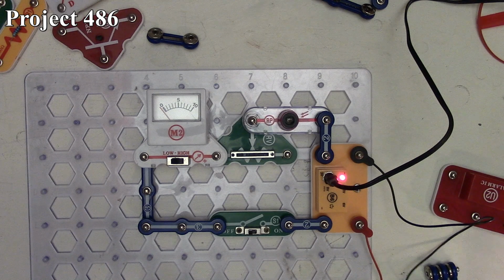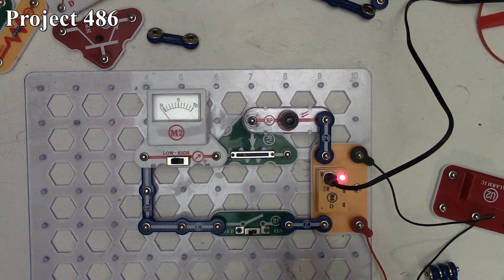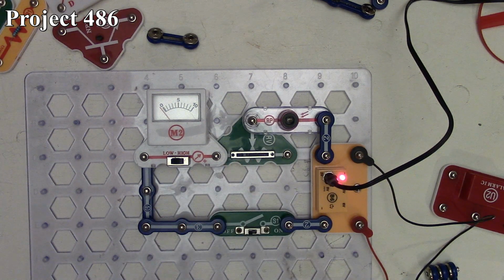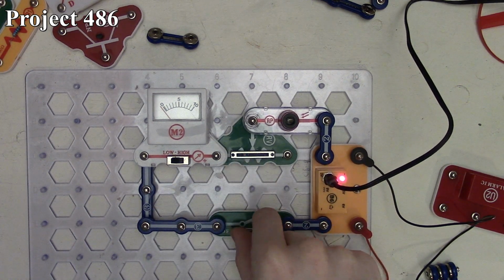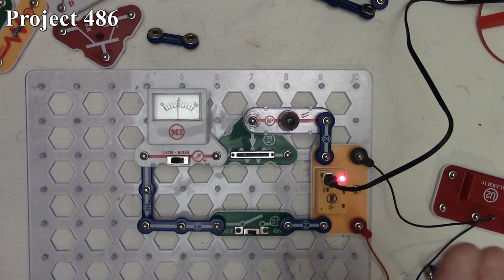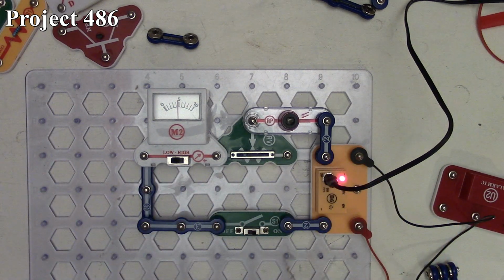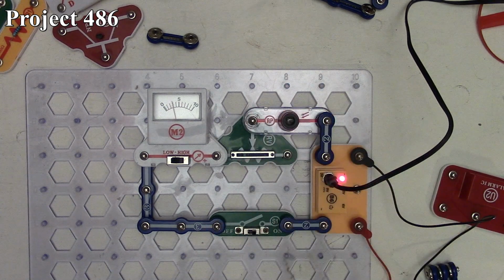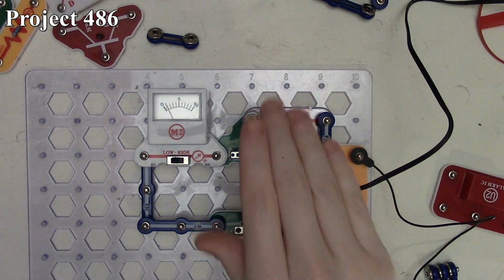So with this project, we have our photoresistor and adjustable resistor here now controlling the current in our circuit. So when we have our variable resistor set all the way to the left, and we turn it on, we get about 5 milliamps of current going through the circuit, because this setup allows the photoresistor to be very sensitive to the amount of light coming into it to affect our circuit. So as you see, putting my hand there briefly makes it deflect almost all the way to 0, because the photoresistor has a lot of effect on the circuit.